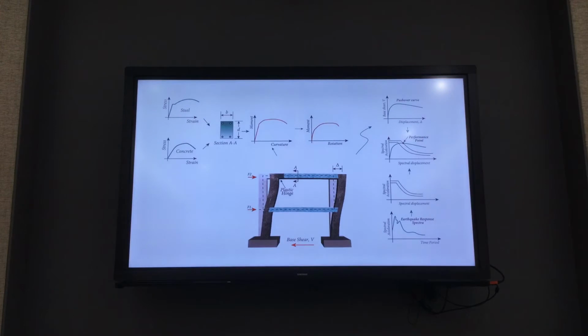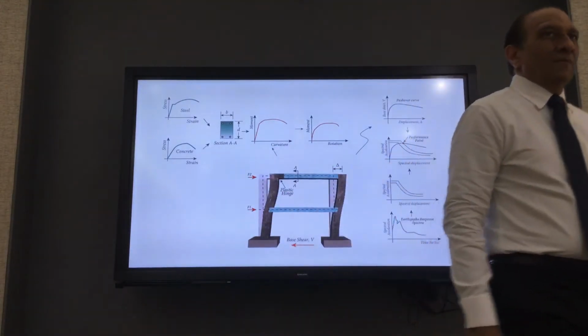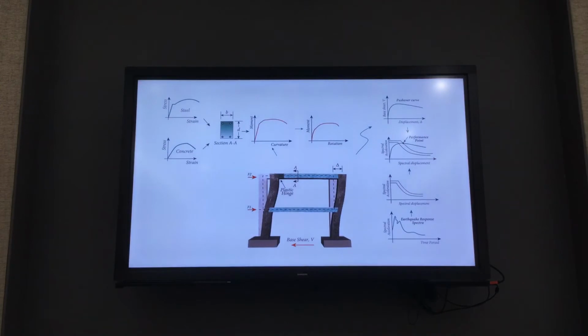That's the problem number one, because you cannot then use it for varying forces which are varying this way and that way, and also for different types of ground motions. That's problem number one with pushover method, that it is corresponding to a known force pattern, which is not that great. So which force pattern people use? Any guess? What is the force pattern we use? Actually, we can use any. This is only 2-story, let's say 3-story. So what pattern you will use for forces?